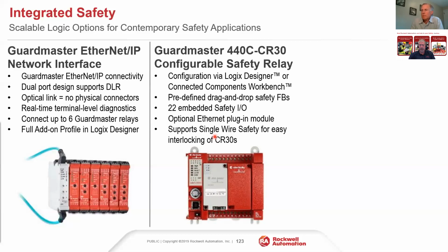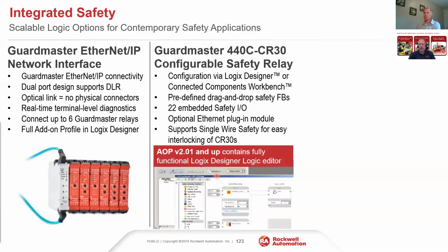Kind of the next layer, if you will, of scalability is a software configurable safety relay. And this is a 22 Safety IO product right here. And this is programmed or configured, managed with either of 2 methods. One is Connected Components Workbench, which is complementary software. The second is through a direct add-on profile to Logix. And when used in Logix, it actually will save that configuration within your ACD file. So it's in one place, very simple to manage the programming.